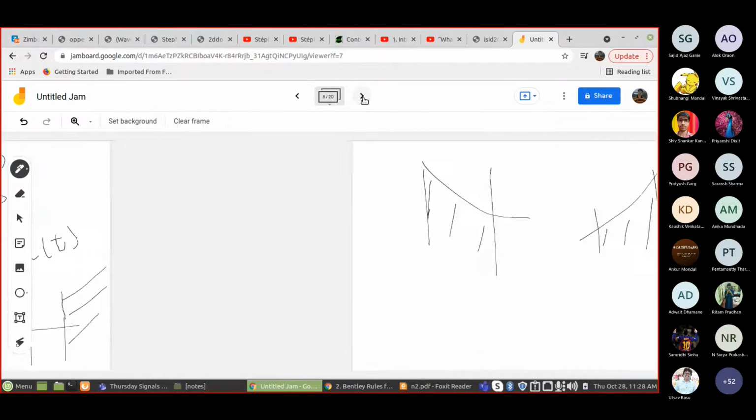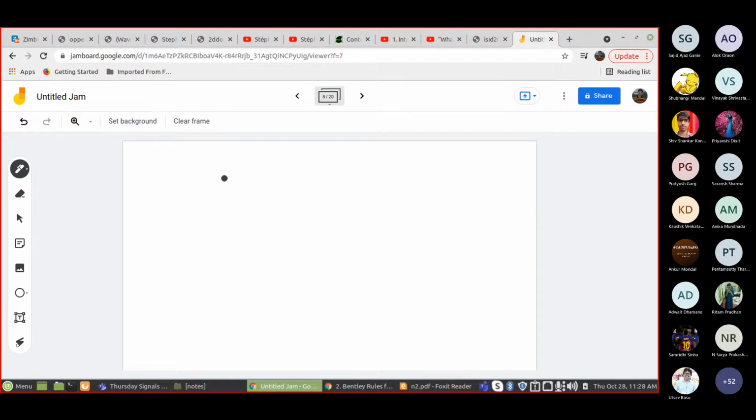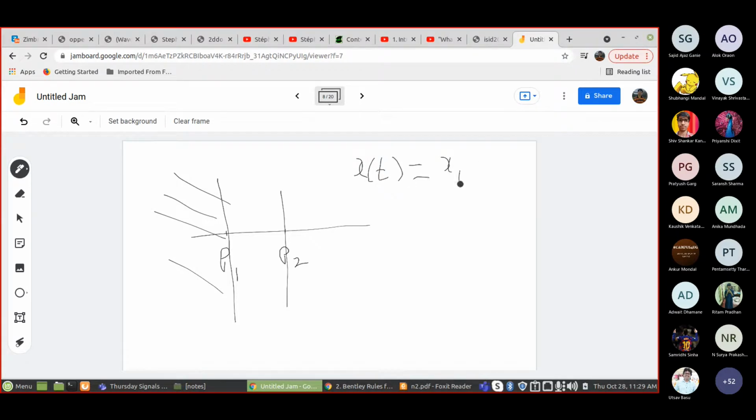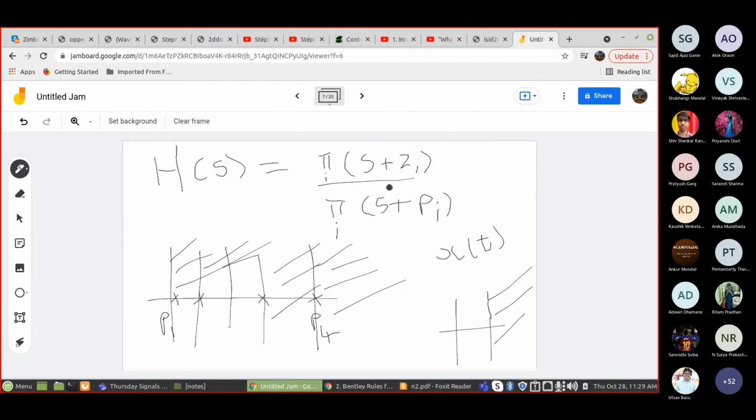On the other hand, if you have mixed signals, both causal and anti-causal, then suppose x1, corresponding to P1, was an anti-causal signal, so you had an ROC like that, and P2, P3, and P4 were here. Our X(s) is the sum of x1, x2, up to x4, obtained by taking the inverse Laplace transform using partial fractions.